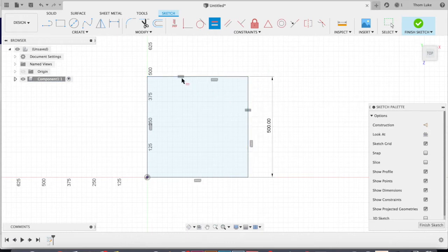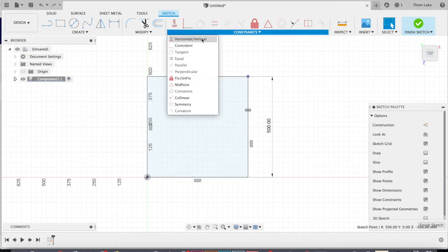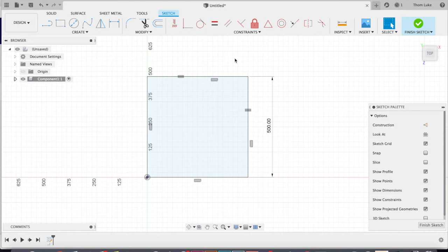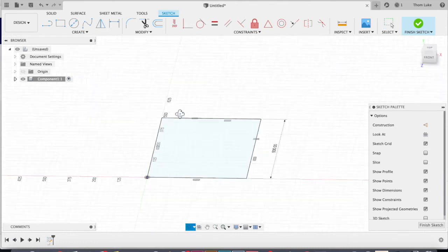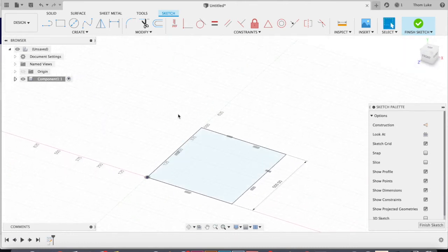See how we now have those two equals symbols have come in? Hit the escape key. Now when I try to drag this, it's equally constrained, and we can see that because it's black. So constraints are essentially geometric methods for us to build controls within our drawing. And by doing so, we build more robust pieces of reference geometry. So a drawing is a piece of reference geometry, I suppose. And that in turn makes things more robust. It's harder to upset downstream.